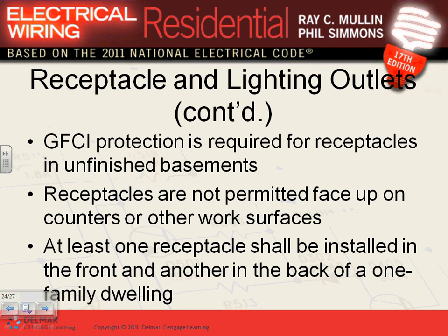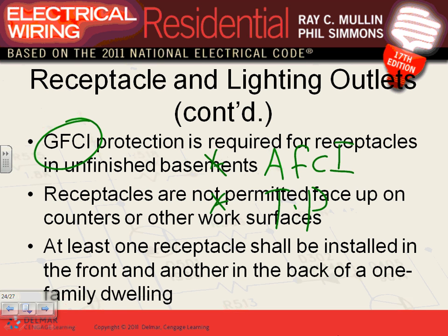Does that make sense? And the arc fault, guys, the way they're coming with the arc fault, I'm sure you've seen them. You have a circuit breaker like this right now, and you put the arc fault circuit interrupter in, and you feed all the lights and all the receptacles from arc fault circuit interrupter circuit breakers. Not just receptacles, both lights and receptacles. Any questions, guys, about arc fault circuit? We talked about the GFCI, the arc fault circuit interrupter, and tamper-proof. All the receptacles have to be tamper-proof, period. All of them, period. Everywhere.